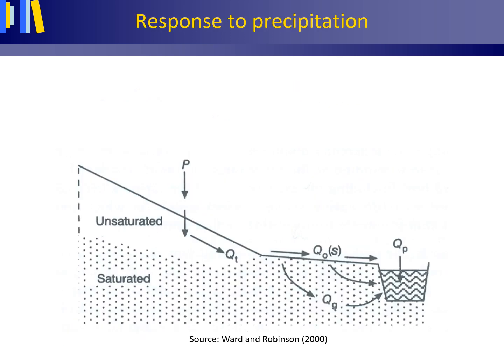Let's start with the drainage basin processes that deliver water rapidly to the stream in humid areas. We will start with groundwater flow. In sloping terrain in humid areas, rainfall events have been observed to raise the shallow water table bordering the stream above the water level of the stream, causing groundwater flow to contribute to the stream flow. Also, during rainfall events in parts of the Netherlands with shallow water tables, groundwater may be transported rapidly through drains and ditches if these are deep enough to cut the rising water table.